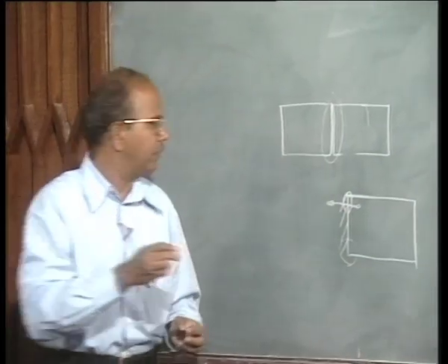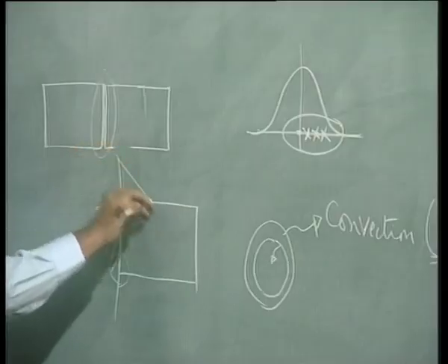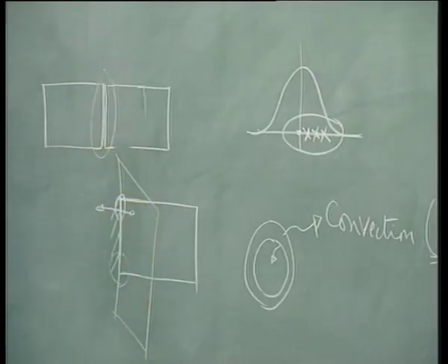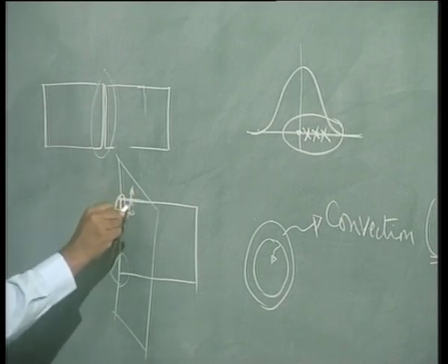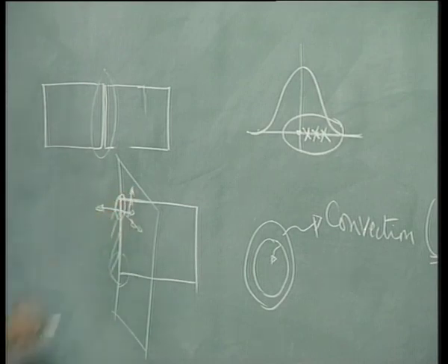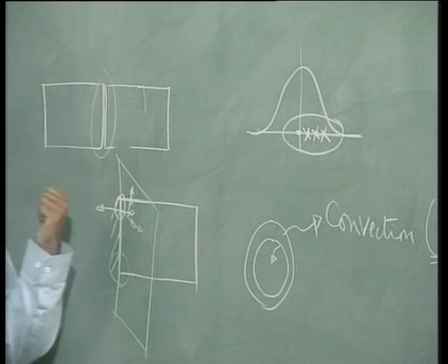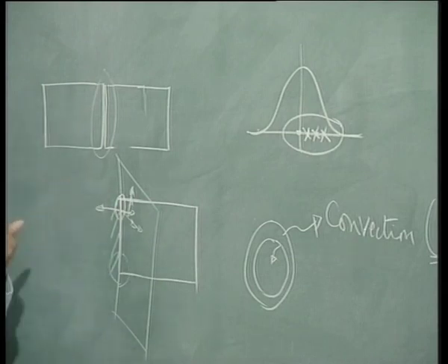Okay, when I put a plane here, that's the symmetry plane, then no rotations will be allowed along the symmetry plane, and perpendicular to the symmetry plane we don't allow displacement, right. This is a symmetry boundary condition you wanted to put, but are you correct in doing it? That's the question.